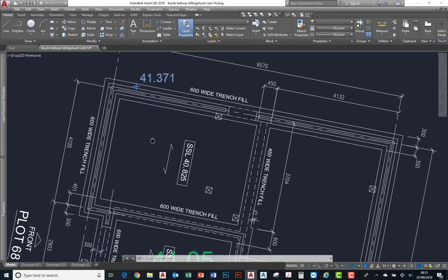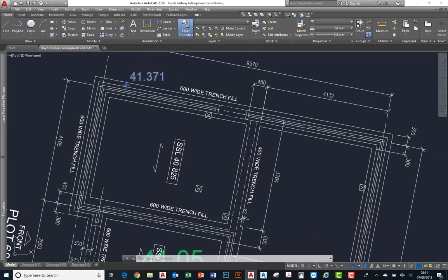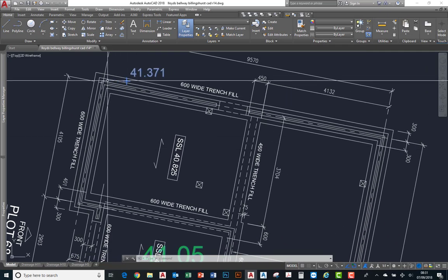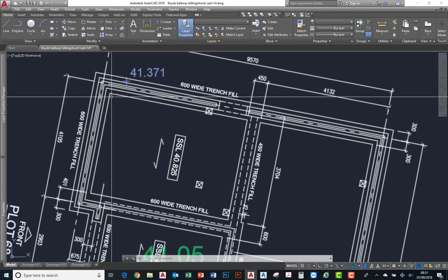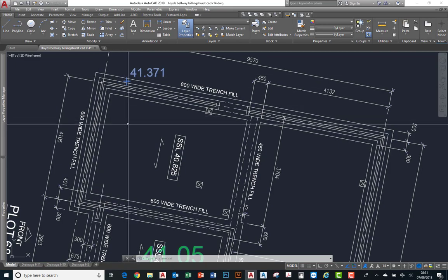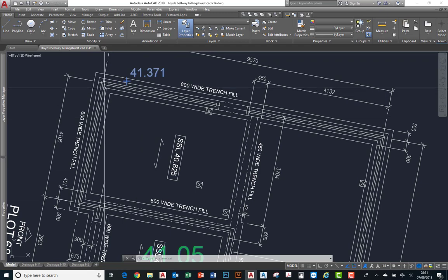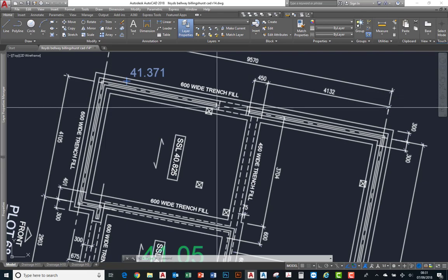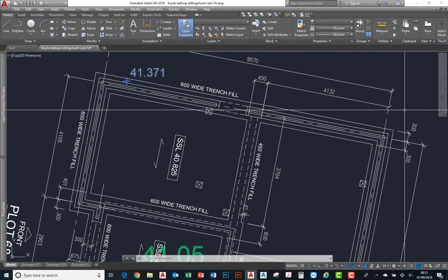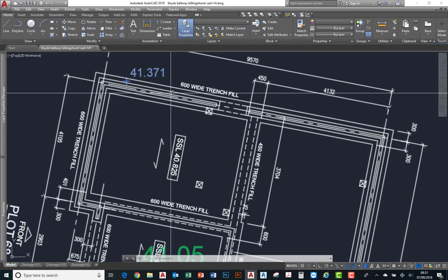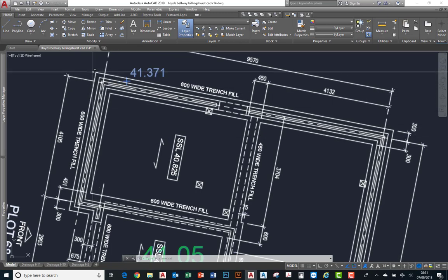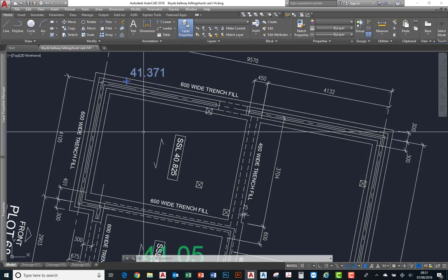What we also need to do is when we create our new lines for our center line for our dig, we want to create those in a different layer so it shows up better, because if we created another line which was white, we'd have real difficulty seeing it over the actual background lines that we've got existing already.